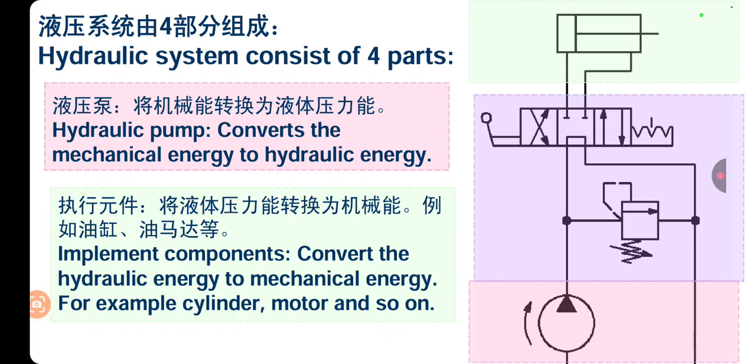The next thing is control valve. There are several types of control valves. It's a flow control valve, direction control valve, pressure control valve. So, control valve. What is control valve? Control valve actually consists of a spool. Now, what is spool? Spool is a mechanical device which always slides within the control valve assembly, means in the housing, and it creates a direction for the hydraulic oil to go towards the actuator. Okay. So this is the function of control valve.